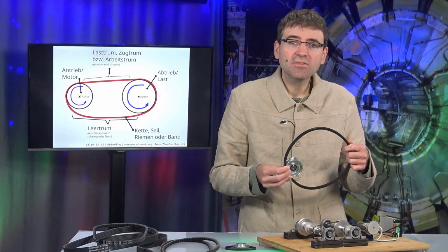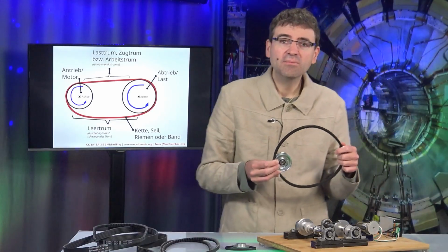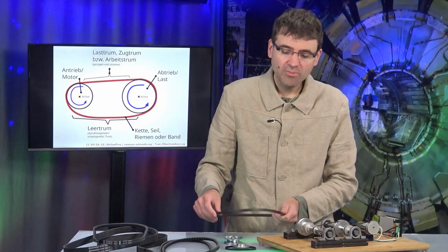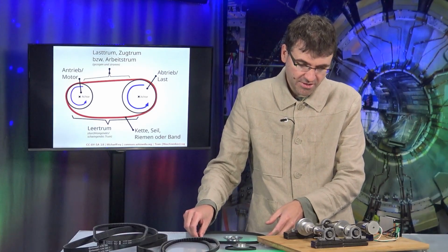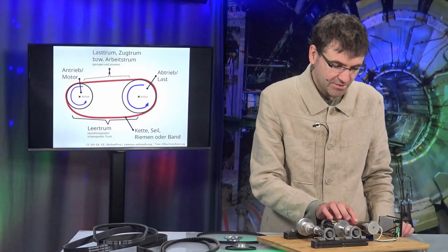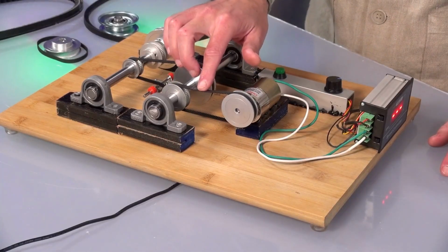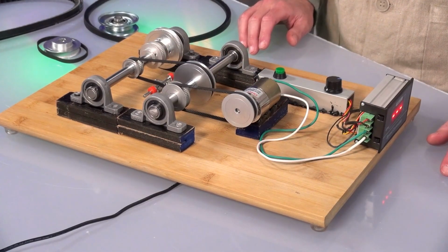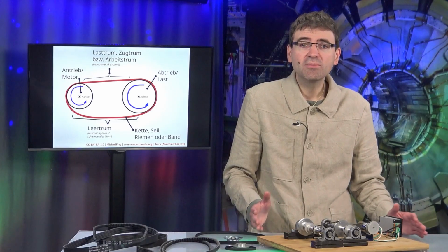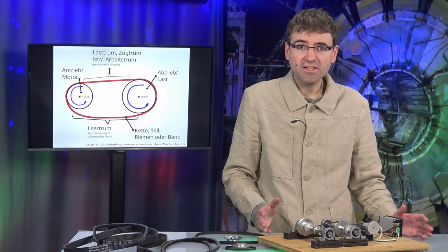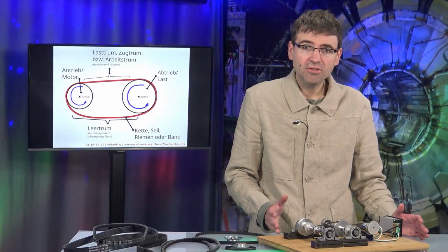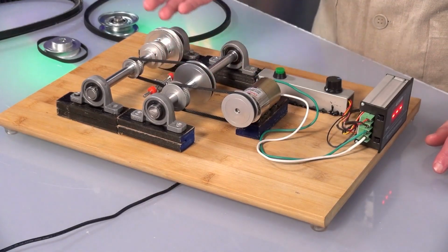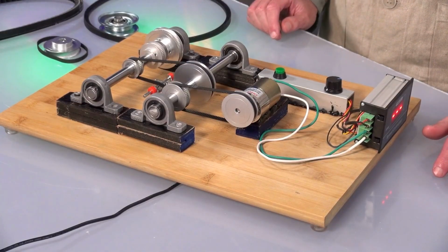For this, there are measuring devices, nowadays also very handy measuring devices, that do this either optically or acoustically. Because we can visualize this, if we look back at our system here, I could now go here with my finger and say, roughly speaking, the tension of this system is correct. But today we possess far superior methods to ascertain this, whether through sound or sight. Why acoustically? Well, the whole thing works according to the same principle as, for example, a string on a musical instrument.